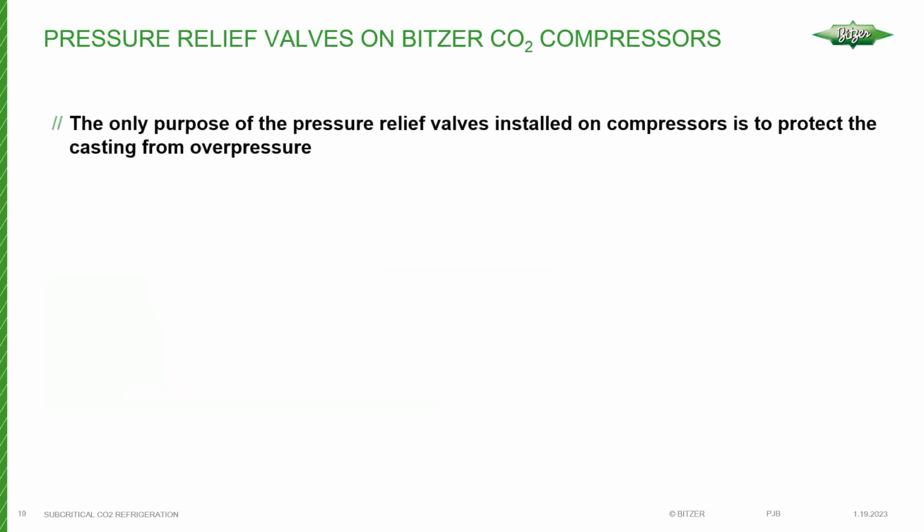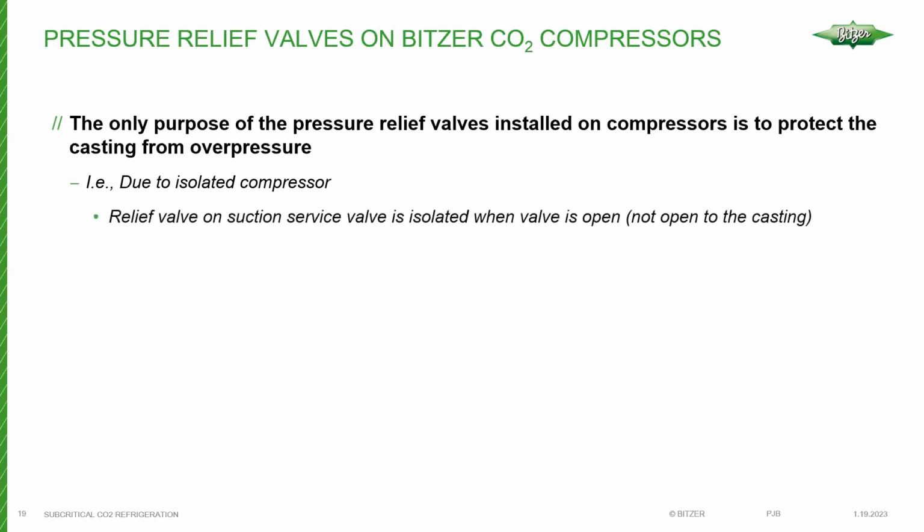And just some notes about the relief valves. The only purpose of these relief valves is to protect the casting from overpressure, okay? So if somebody was to inadvertently isolate the compressor, leave the discharge service valve closed, and then start up the compressor, we talked about the pressure increase. The rate of pressure increase with CO2 is very high, and the relief valve needs to be there to protect the compressor in this case.